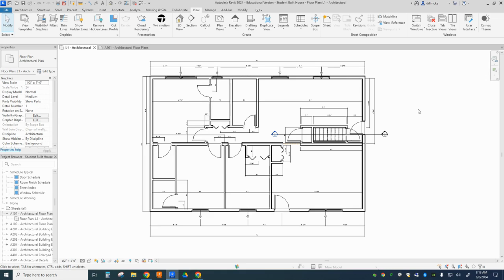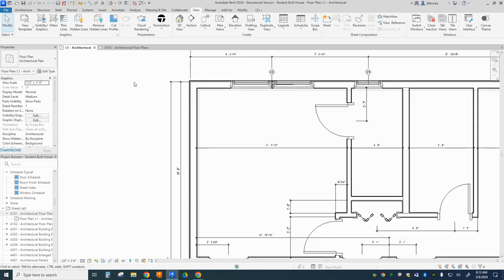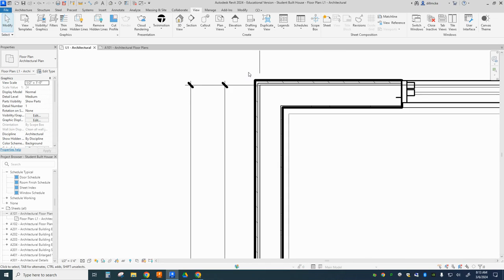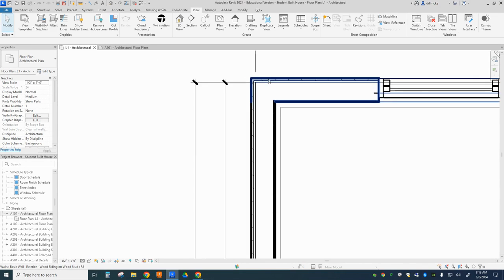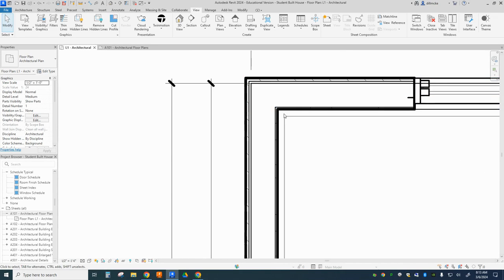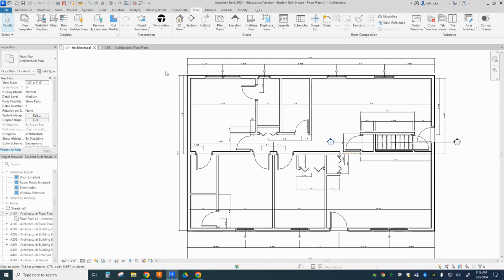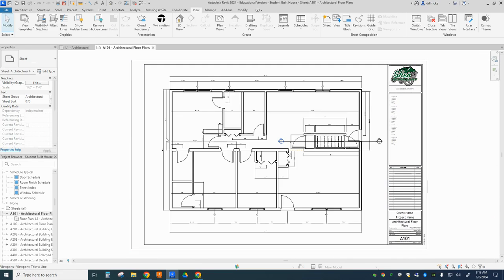All right, for this part of the drawing set, we are going to turn this floor plan for the level 1 that we've been working on, with all our dimensions and our window and door tags and everything, into just a framing plan. That means we're going to take some of these layers of our walls that are not framing, like the exterior siding and plywood, the interior drywall, everything that's not framing, and we're going to hide that stuff